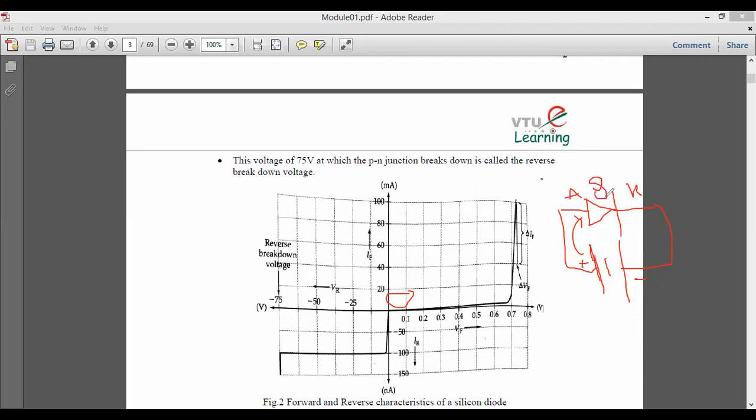If the diode is a silicon diode, and you have applied a voltage of 0.1 volt, is it still forward biased? The answer is yes. The diode is forward biased, but it will not be in the conducting state because it has to reach 0.7. If 0.1 volt is less than 0.7 volt, then we cannot say that the diode will conduct. The amount of voltage is too small.